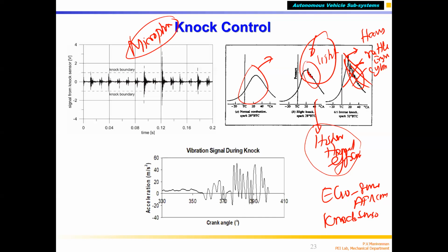So the best thing is to reduce the gear. You reduce the gear, maybe to second gear again. Then if you try to accelerate, the vehicle will start accelerating. If you don't reduce the gear from fourth gear to second gear, you will hear the engine making heavy noise, as if something is happening inside. Huge noise, explosion, vibration, all these things. That is nothing but knocking.